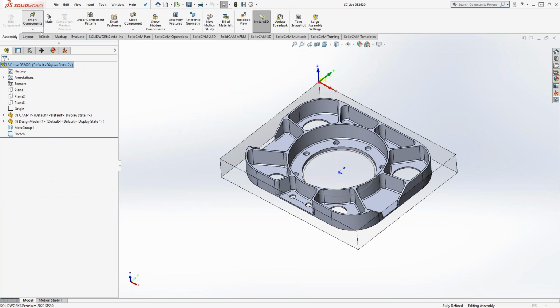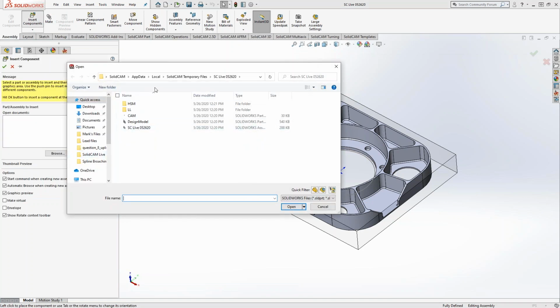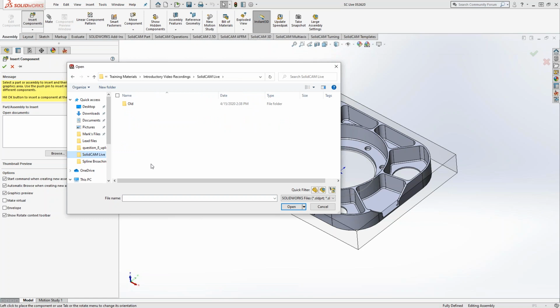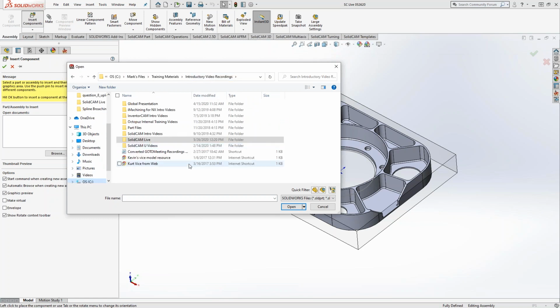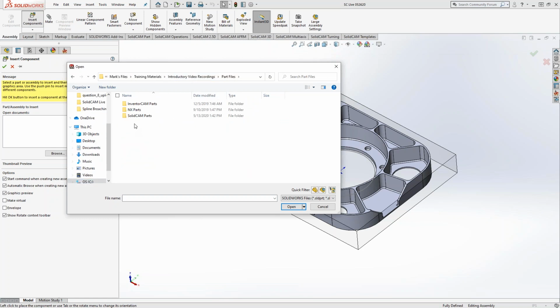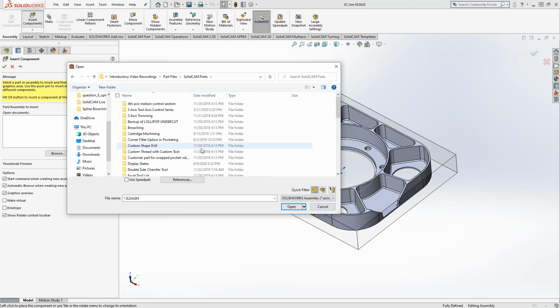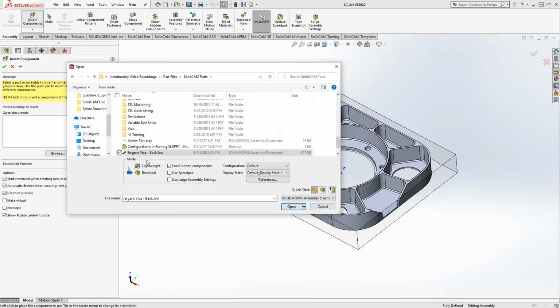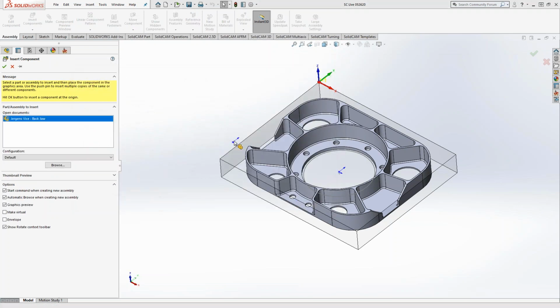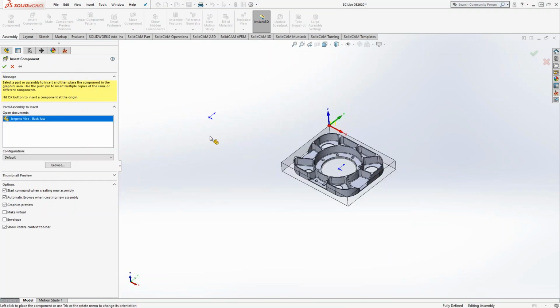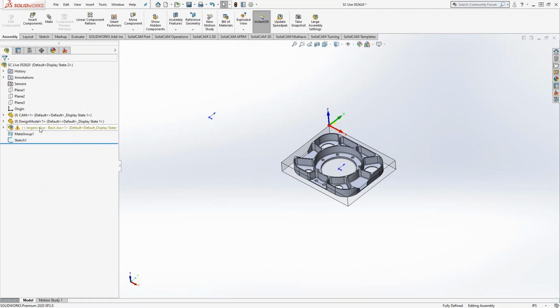The reason I mentioned that, and we probably mentioned this before in the live classes, is that with iMachining and a lot of our toolpaths in there, it does have full fixture detection and avoidance. So what Mark can do is put a fixture in here, and then when he goes to pick his toolpath, he doesn't have to worry about that vise being there. Now, the majority of the time for you guys, you won't need to put a vise in there just because you know your machines better than any one of us. So you'll know with that material how much is sticking out, if we can get in that specific area, all that stuff.